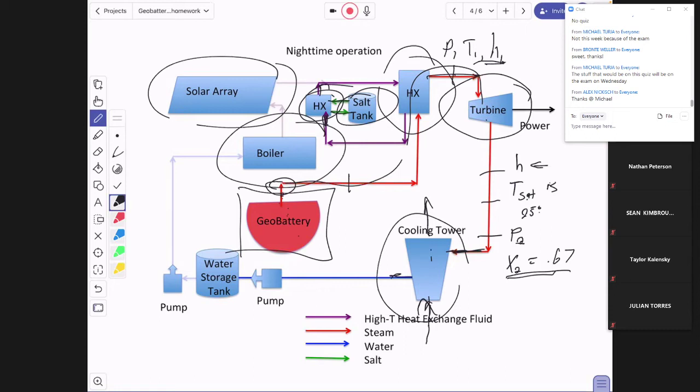And so since we're taking out so much energy here, then we cool it down to get to a low temperature, 25 here. The boiler, the same thing: energy goes in, probably through heat. We've got a massive water coming in, and we've got some massive steam coming out. Mass of water in is equal to the mass of steam out.